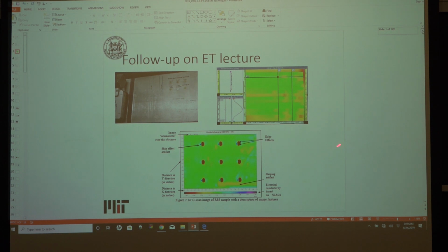So you can see the difference between the two. There are some ways that you can use an off-the-shelf technique to improve resolution. One of them is known as multiplexing. If we're talking ultrasonics, it's the way in which the ultrasonic sound beams are actually timed. They time the sequencing of how they send the various channels through the sample. That's the sectorial scans, and those are also the C scans.